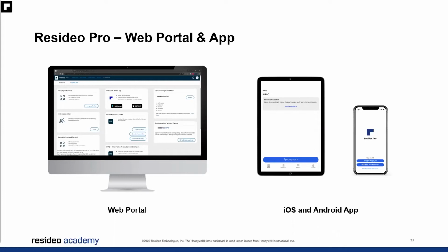So you can easily invite homeowners to use their smartphone app so they can jump right into the Wi-Fi setup. And this will allow them to skip the technical process and just make it easy. So all they really have to do is enter their Wi-Fi credentials and register the device. Creates an easier install. So instead of connecting through Wi-Fi, the T6 Pro thermostat can be used with the Resideo Pro app to connect via Bluetooth to remove some of those complexities around different phone types and systems, and also routers.